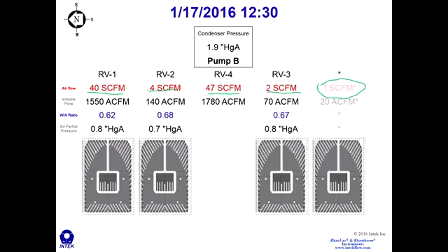But here, let's take a look at what information we can gather by having these measurements on the suction side of the vacuum equipment. Number one, we can see that air and leakage is very high in this bundle and low in the others. Also, we can see that they're operating one vacuum pump, and most of the vacuum pump's capacity is on this one bundle.